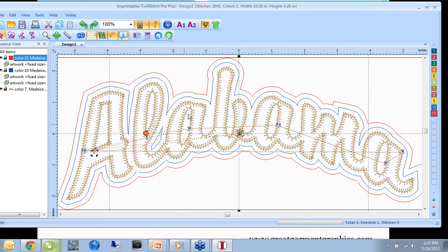So if that's the first one, I may or may not need placement lines for these depending upon what type of process I'm using. If I'm using a roll cutter where I'm doing single layers, or if I'm hand cutting it in single layers, we want to have a placement line each time because you're going to lay the fabric down and then put it on there and then cut it out by hand, or I've got separate pieces. Maybe I'm ordering pre-cuts that have 2 or 3 layers already to it, or if I'm using a flatbed cutter or a laser, I can do those in one shot.